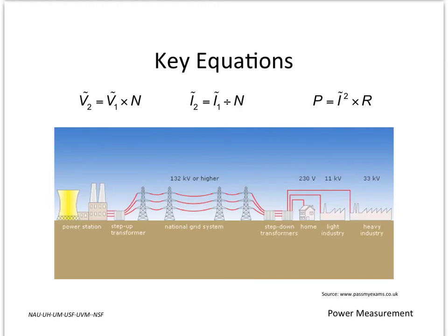The previous example was that of a step-down transformer, as the voltage was lower at the secondary than at the primary. However, to reduce the current flowing in a transmission line, we use a step-up transformer to convert the power signal coming from the power station to a very high voltage, relatively low current signal. Once at the distribution point, that is, your neighborhood, this signal is retransformed using a step-down transformer to a lower voltage, higher current signal for use in the home. This strategy reduces the I²R losses that occur in the transmission line.